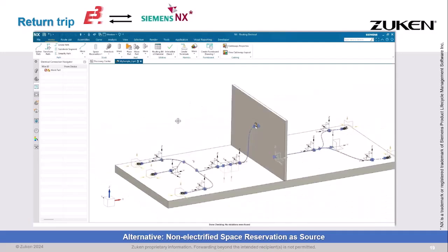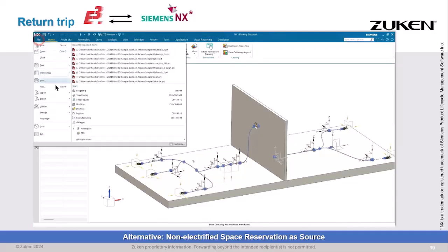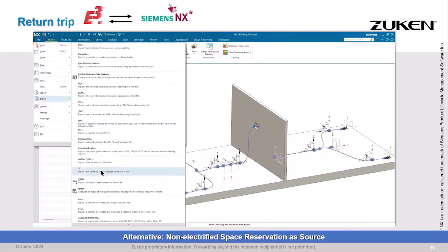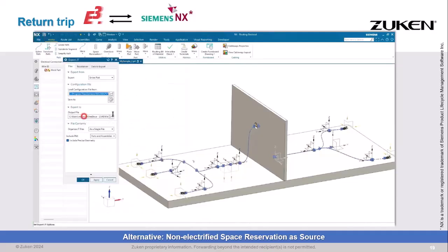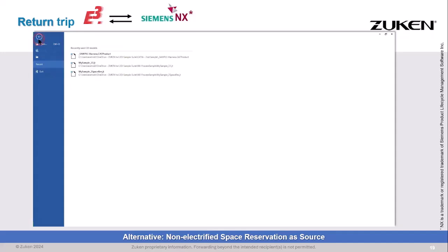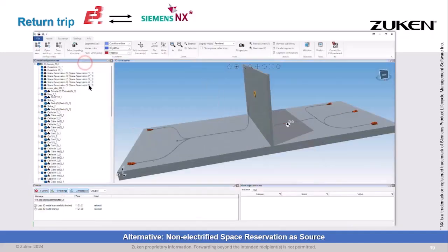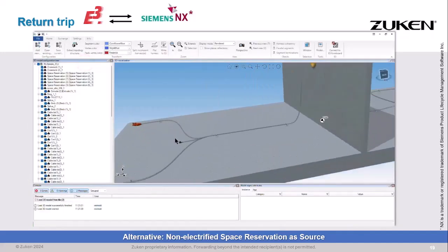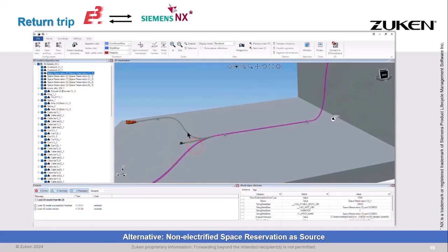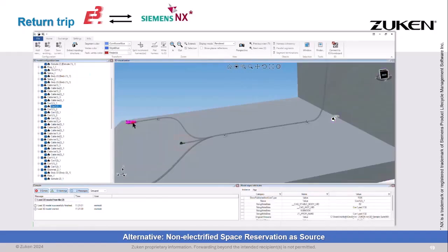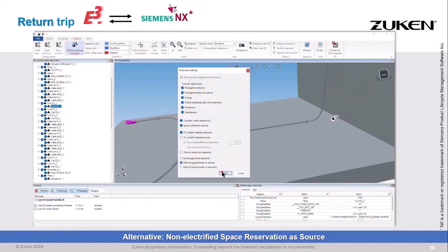Once this is complete, we then export this information. Again, it's going to be a JT file. And this can also be read into our 3D transformer. Once read into the transformer, we can then flatten and generate our Formboard harness.